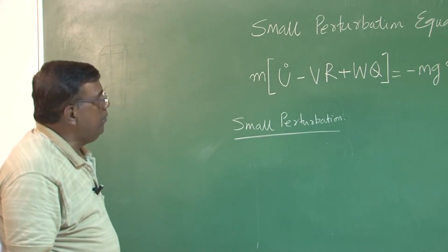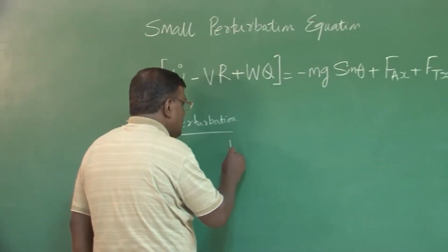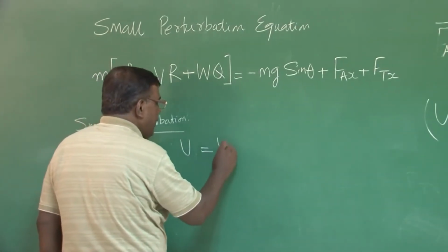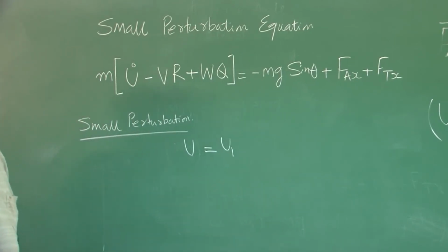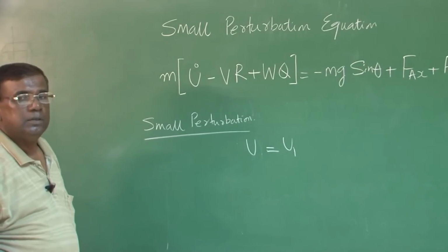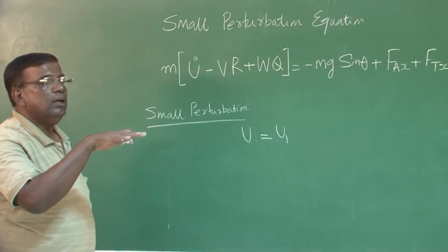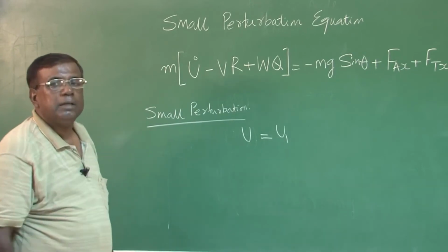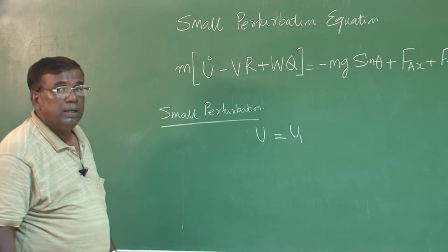And under that small perturbation concept, we can use that if I am flying at a steady state condition u1, let us say the cruise, we are introducing disturbances about cruise. So, the plane is cruising, I give a small perturbation and see what is happening to the machine dynamically, right. With this coming back, once the disturbance is withdrawn, what is it actually doing.